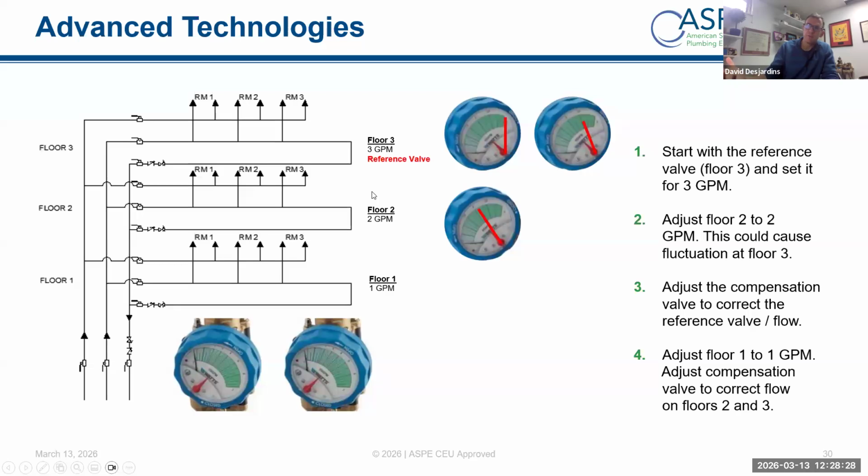So I start my furthest, again, if you can imagine this, I have balancing on my risers and branches. I have multiple of these. But I could set this in, and as I turn the bezel here, you can see the impact on flow. So instead of looking at the chart and then trying to figure that out, I know I need 3 gallons of recirc flow up here. You can dial this, and that black needle will just take you to where you have to go.